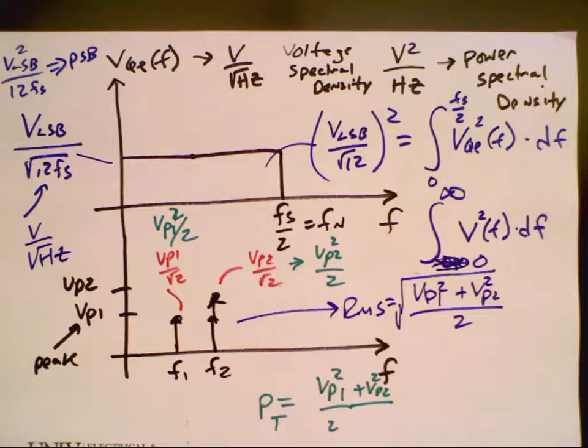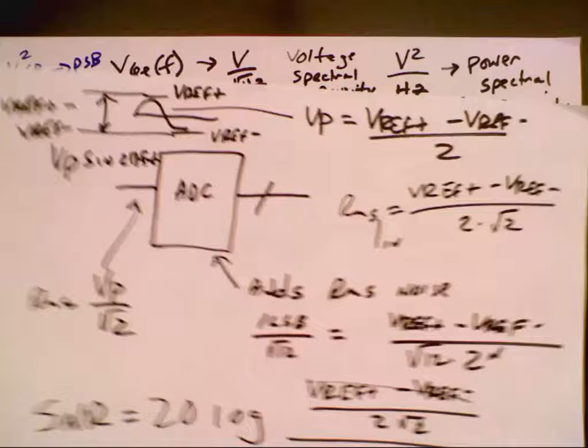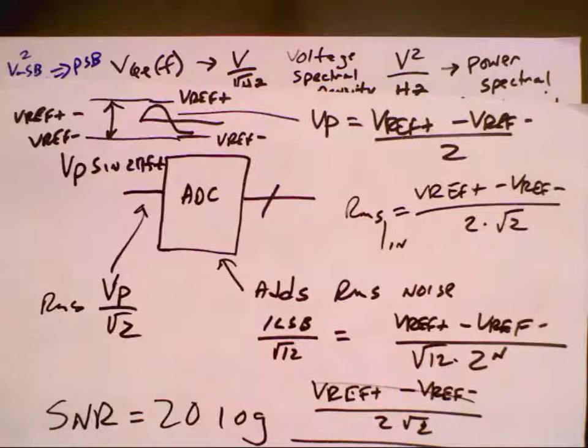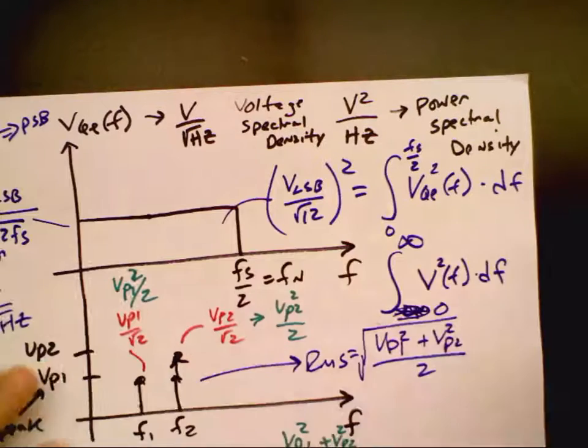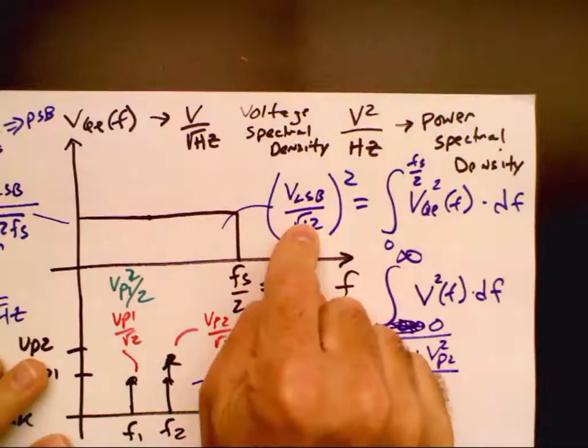Okay, a simple example of coherent sampling is if I put a DC signal into my ADC. I could get zero quantization noise if I put it right on the border, at the happy spot there. Or I could get a quantization noise which is a full 1/2 LSB or minus 1/2 LSB, and that's considerably different than the quantization noise that I calculate as VLSB over root 12.